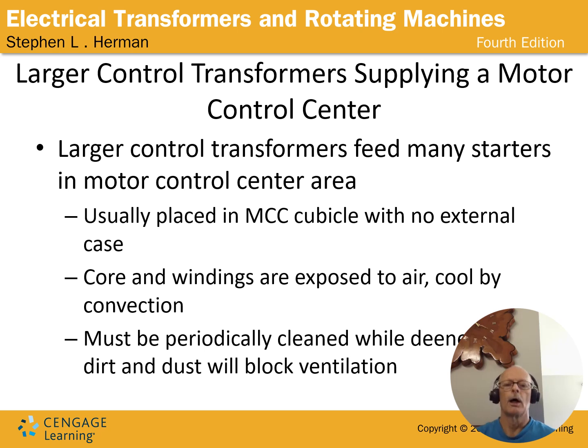It's not being pushed. So one of the things you need to know is if the transformer is dirty or if there's not good airflow, it's not going to have good heat transfer. And if you don't have good heat transfer, eventually that transformer will overheat and burn up.